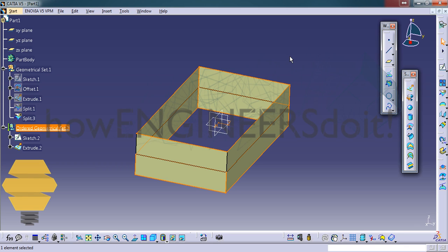As I have explained, both have their advantages and disadvantages. If you're not sure what exactly you will have to implement in between your design, or maybe you have to put in a new element and interlink all the remaining, then I think going for a normal geometric set would be a good idea. And also, if you are creating certain elements which you are so sure this is how it goes, this is the best way you can make it, and you're not going to implement any new element and then change the ordering rules, if you're sure about the ordering rules, then it's better you use the ordered geometric set as well in the same design.